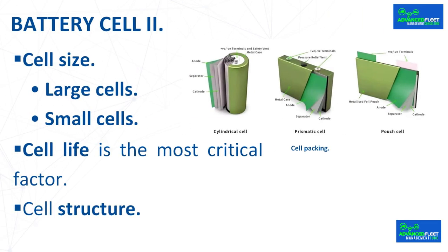They dissipate heat better, but also complicate cooling systems. Cooling the 200 or 300 cells of most current cars is not the same as the nearly 8,000 of the 85 kilowatt hours Model S. Furthermore, the greater the number of cells, the more complicated the BMS becomes, and of course all this is much more expensive than in a pack made in the other simpler way.